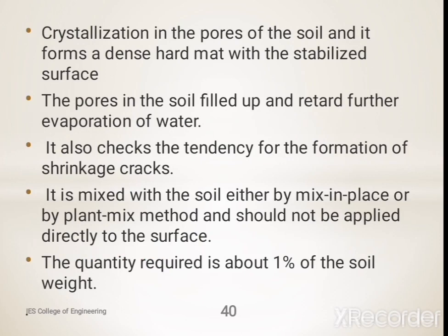Crystallization occurs in the pores of the soil, and it forms a dense hard mat with the stabilized surface. The pores in the soil are filled up and retard further evaporation of water. It also checks the tendency for the formation of shrinkage cracks. It is mixed with soil either by mix-in-place method or plant mix method. It should not be applied directly to the surface. The quantity required is about 1% of the soil weight.